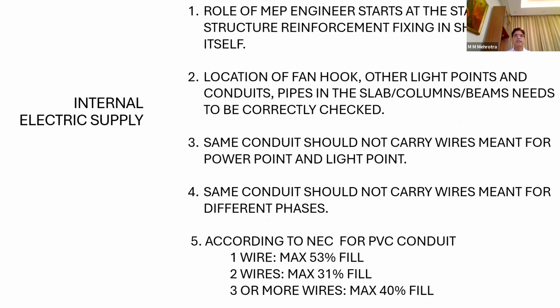Now I am an MEP engineer, an electrical engineer. The project is predominantly managed by civil engineers, so they are not bothered about what is happening to your electrical and mechanical things. So when the casting is being done, the MEP engineer is required to visit the site first, when the shuttering is being fixed and the reinforcement is being fixed.